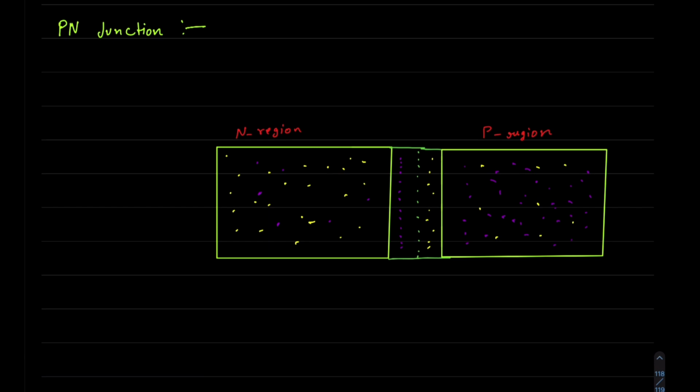So basically, the behavior of the PN junction with regard to the potential barrier's width produces an asymmetrical conducting two-terminal device. So this becomes a two-terminal device, our diode, right? It has two terminals. This is also known as the PN junction diode, right? So this device, this PN junction material mixed together, when attached to an external battery source, is then known as a PN junction diode.